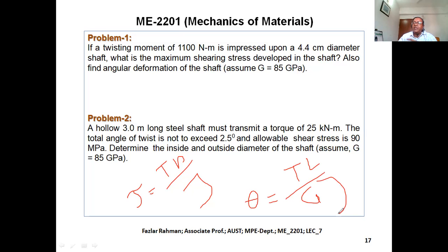What they do, they update the spring, increase the height, but they are not able to increase the capacity of the shaft because it is designed for 500 ton, or might be it has some factor of safety that they might design with 6 ton. But you load it, almost make it double. So their life is reduced. Initially able to carry the load, but supposed to be run for 10 years or 15 years, but after 5 years, it breaks down. Okay.